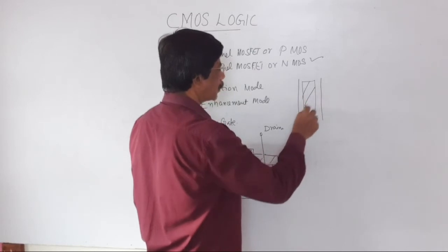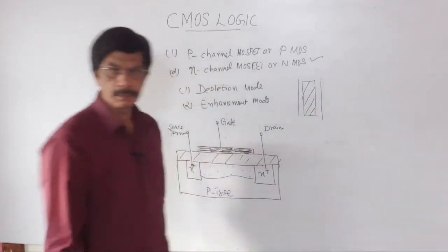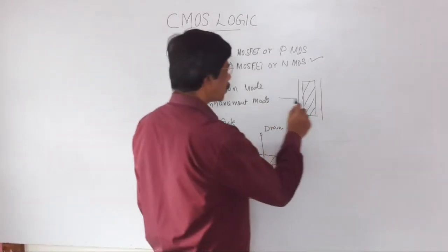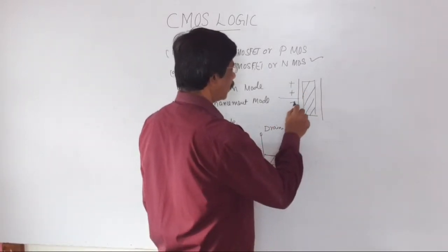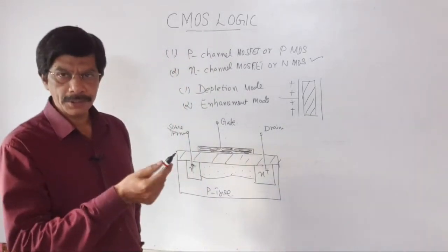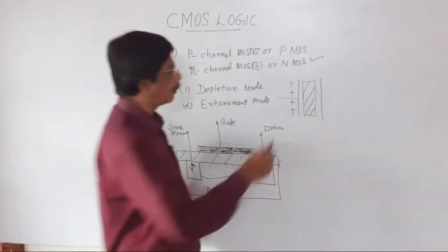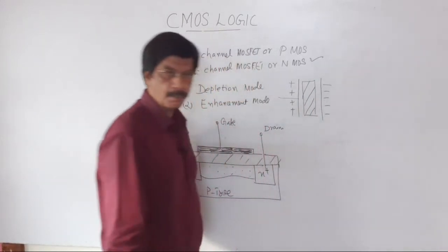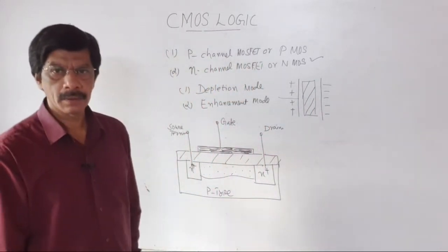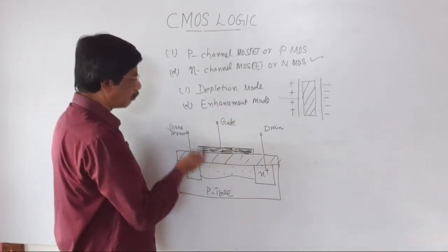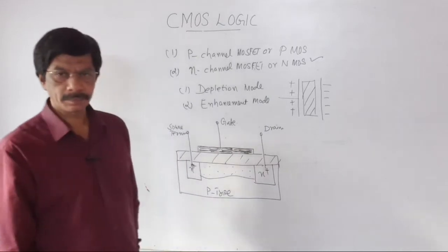That medium is known as the dielectric medium. When positive charges are deposited on one side of the plate, equal negative charges are induced on the opposite side of the plate. This is the concept of parallel plate capacitors. The same concept is used in the MOSFET transistor.